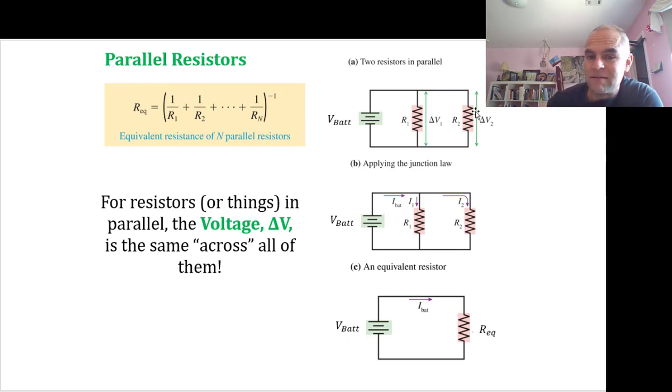One of the things that I'm going to want you to see, and I'm going to show you why this is the case, is that when you put a few resistors in different configurations, it's the equivalent of having one resistor. So in other words, these two here that are in parallel can be equated to just one resistor right here. And I will derive why this is the case soon, but the equation for finding that out is this one here.